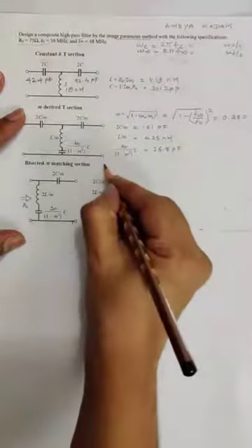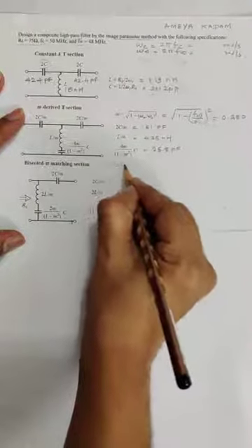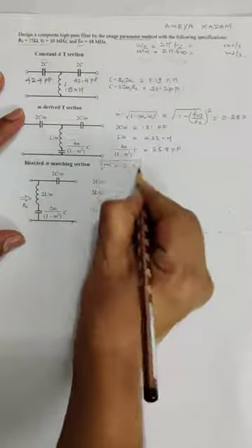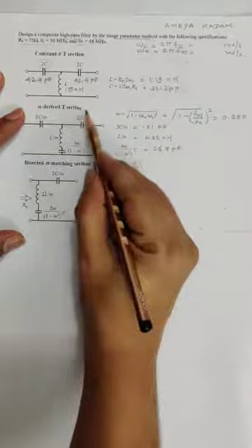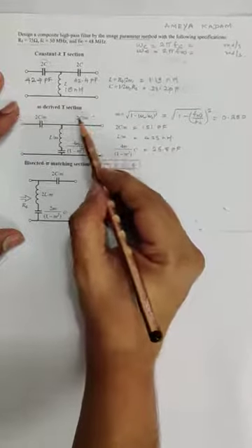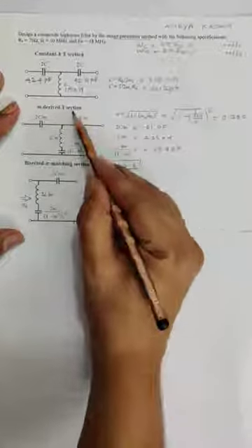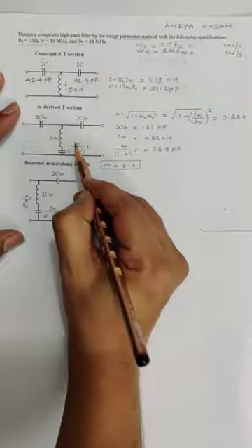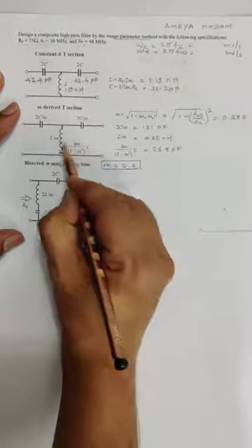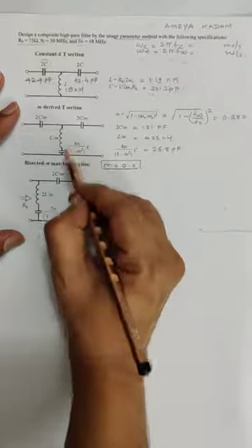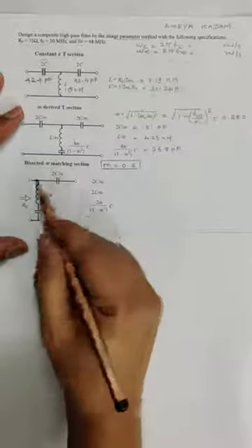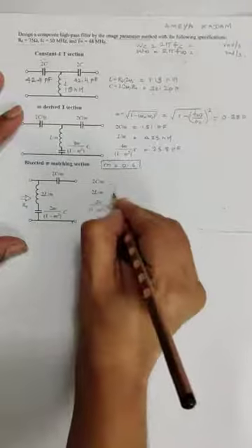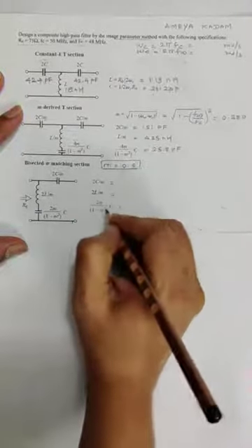So we have the bisected pi matching network where the M value is 0.6. As I mentioned in the last lecture, we have to copy this part of the network as it is over here, and one has to split this 4. So 4 is in the numerator, so we'll split like this, 2 over here and the remaining 2 over here. One can memorize in this manner, and they can calculate the component values.